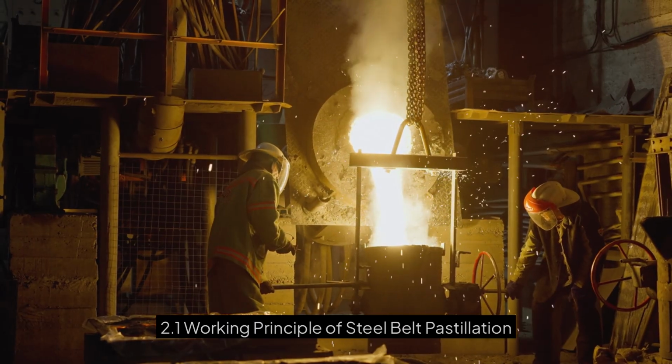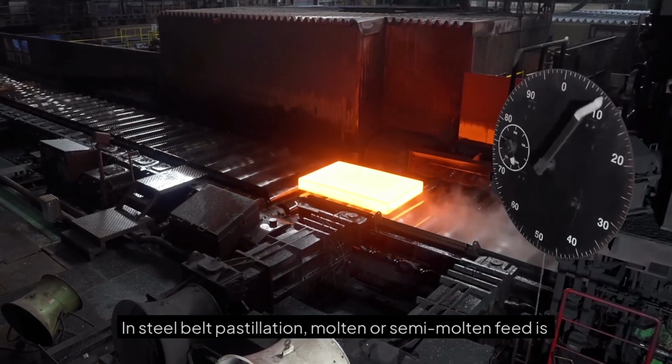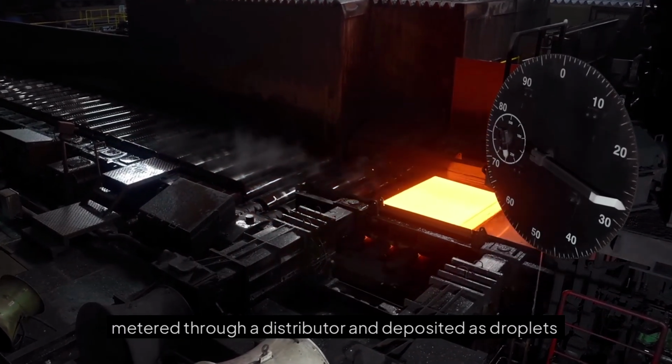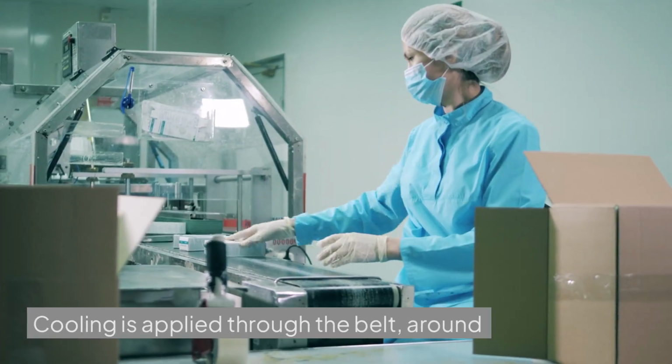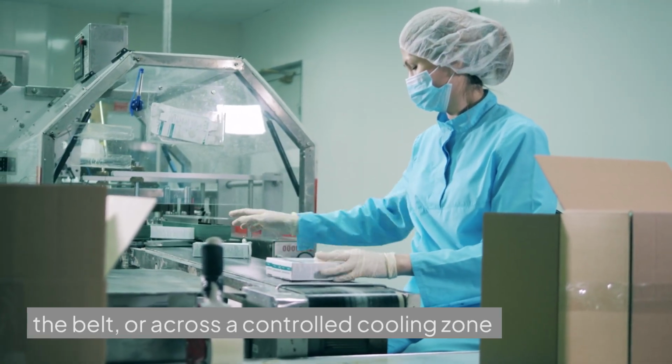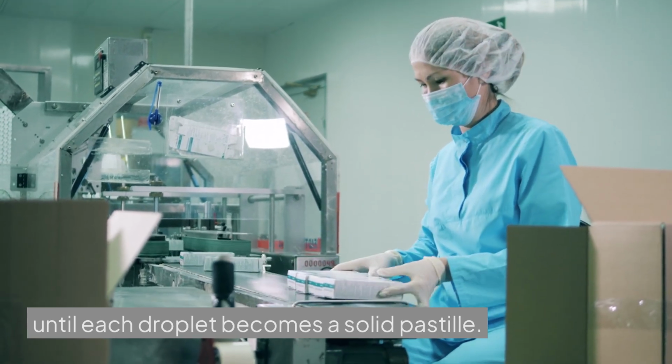2.1 Working principle of steel belt pastillation. In steel belt pastillation, molten or semi-molten feed is metered through a distributor and deposited as droplets onto a moving stainless steel belt. Cooling is applied through the belt, around the belt, or across a controlled cooling zone until each droplet becomes a solid pastille.